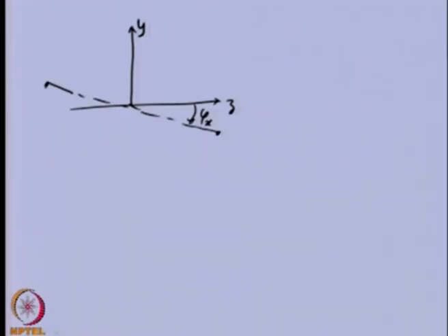So, the spring which is attached here will give force in the downward direction, because that will get stretched. Here it will get compressed, so it will give a force opposite to the compression, and you can see that this particular distance is the actual compression of the spring. If we take the total length of the rotor as L, from here to here, then this distance will be L by 2 into phi x. So, compression of the spring will be this much.